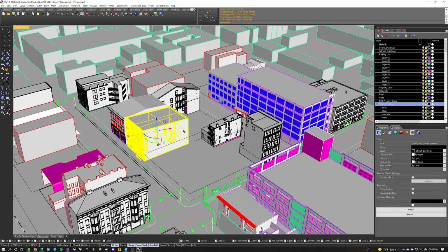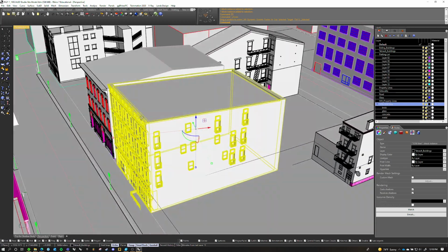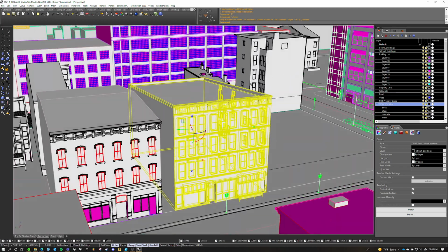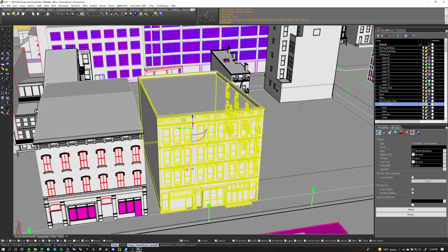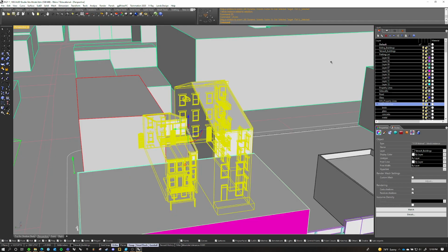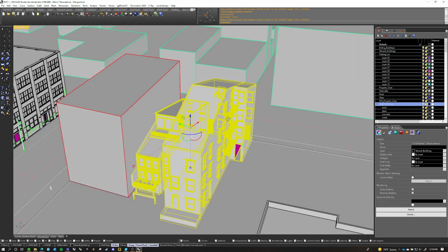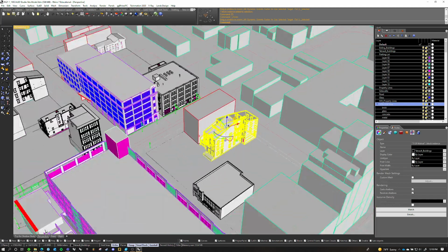And also, if you choose your model and press ZS and enter or space, it'll reorient your viewport around that object. So if I'm working over here and I'm trying to model over here at the same time, or over here, what I would want to do is click that object, type in ZS, enter or space, and then that'll be the new focus.